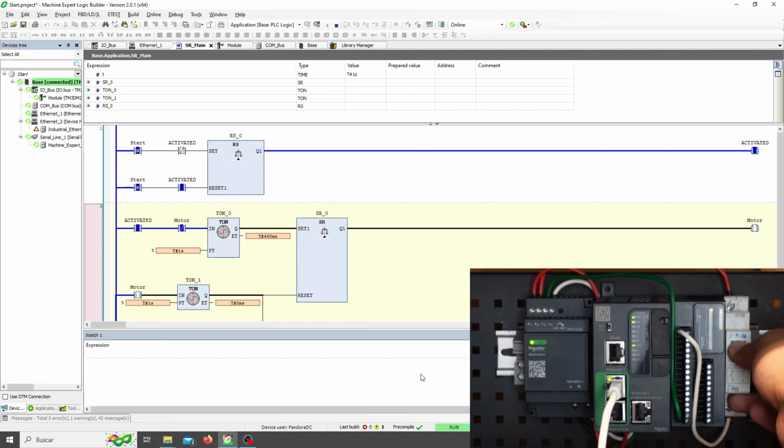Check that if I press here, there is no behavior or deactivation. But when the button is released, okay, everything works. Why? Here I used contacts with edge detector. Which edge? The negation edge, or falling edge, is detected. Only in that situation is the contact activated.